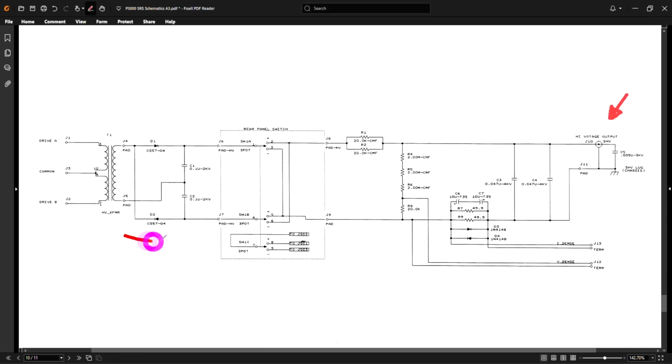And if you look, all they've done is that they have added a voltage doubler. So instead of a full bridge rectifier, now we have the voltage doubler achieved with D1, D2, C1, and C2. The rest of the circuit fundamentally stays the same, except the voltage division ratio has to change because now you have twice as much voltage, and then you have to make sure that all these different capacitors and diodes that you're using are now rated to the higher voltage in the circuit.